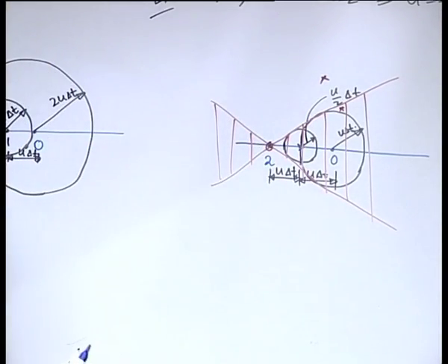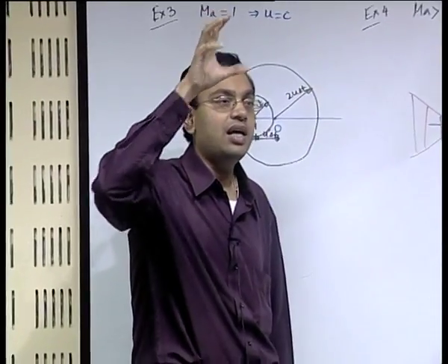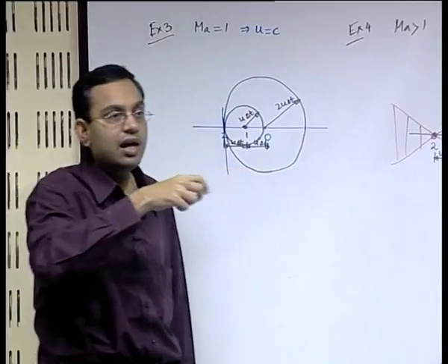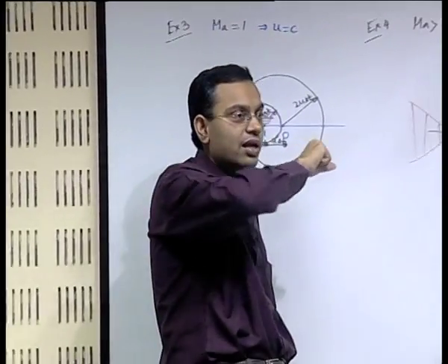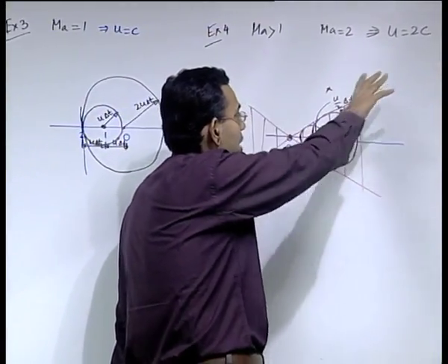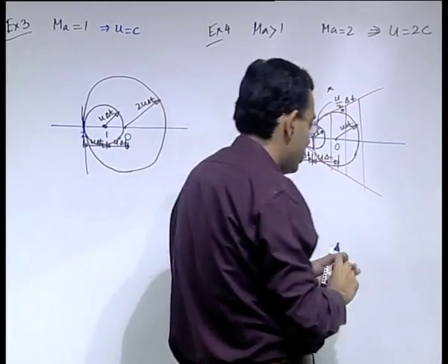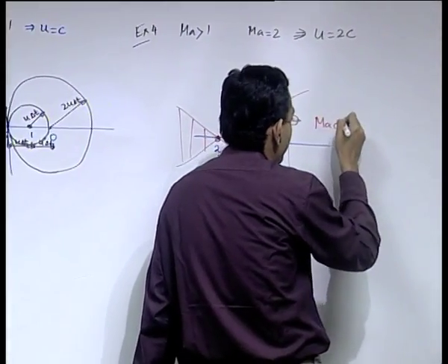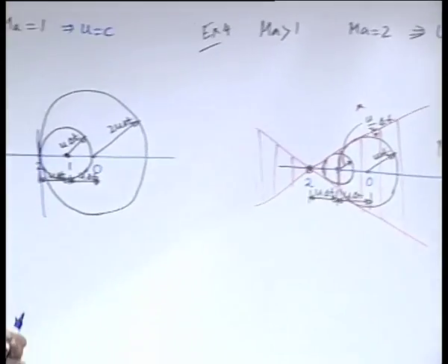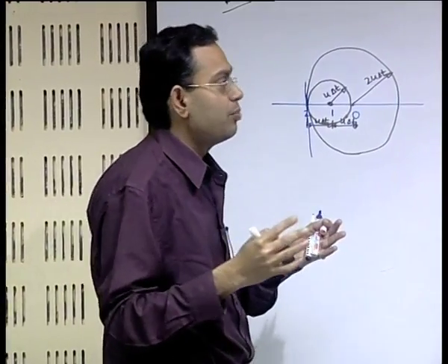You can see sometimes, if you have seen such physical examples, jet planes moving in the sky at a very high speed. These are supersonic speeds, and at those high speeds you will see that they emit emissions which will have their boundary like this in a conical fashion. So, this in compressible flow jargon is known as Mach cone. It is like an imaginary cone, within which you have your disturbance propagation effect felt.